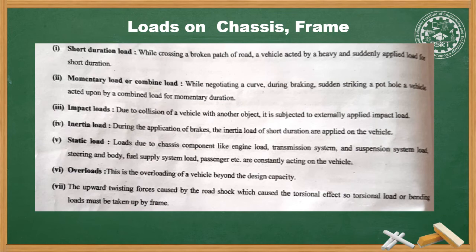Overload. Overloading of the vehicle is loading the vehicle beyond the design capacity. And last, the upward twisting forces caused by road shock which cause the torsional effect. So torsional load or bending load must also be taken up by the frame.